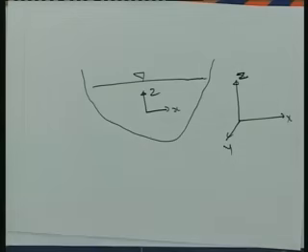Even though the fluid flow is definitely 3 dimensional in nature, we are simplifying the 3 dimensional fluid flow into 2 dimensional, since it will be very easy to analyze and to interpret the results also. So, depending upon the case, depending upon the fluid flow problem, we can consider a 3 dimensional flow as 2 dimensional, so that the accuracy of the results is not much affected.